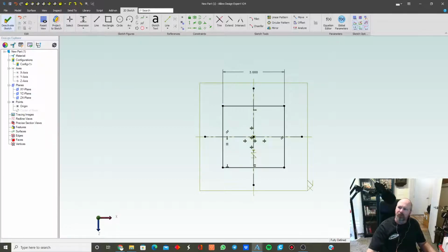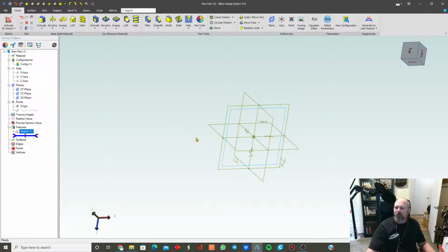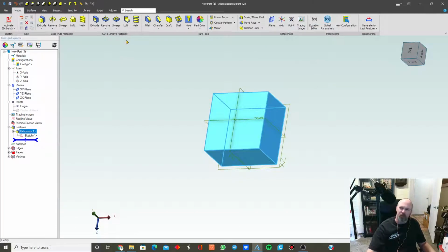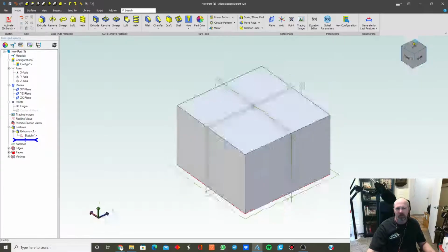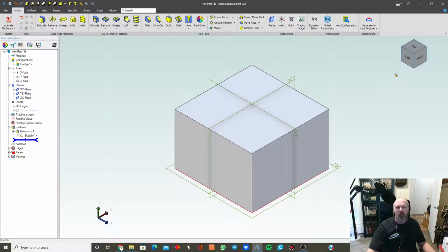You can deselect the activate sketch, and we're back into that mode again, right? So see, our drawing is highlighted in light blue on this one. We'll go back up to extrude, and you can see it bosses something out for us. It just defaults to 5 inches. We want to make this 2 inches. So our piece is only going to be 2 inches tall. And then we hit that. You can hit the same corner. We can change perspective on it or whatever, and you can rotate or cube around. Just kind of nice to have those quick view settings.